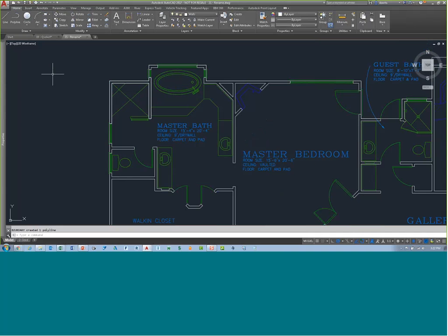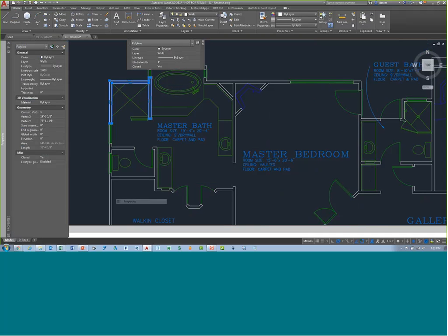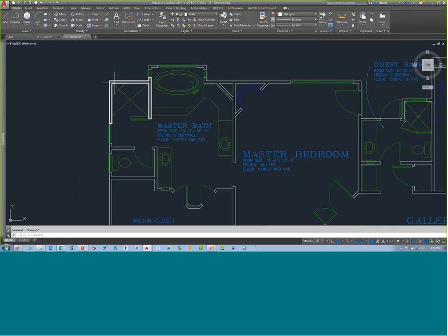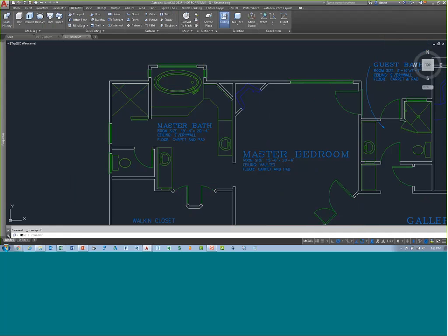And if you do this, then you can select the boundary, and you can get a lot of property value information. It tells you a lot of rich data, area, length. But for the purposes of extruding this boundary line up to give that wall a sense of 3D thickness, we can switch over to turning on 3D tools and using the press pull. The press pull will see the boundary line, select it, and automatically ask for a Z height, so I'll put in 8 feet, and I hit enter and I'm done.